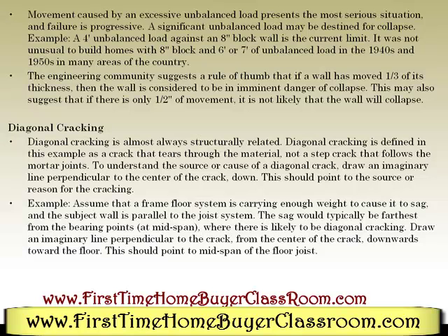The engineering community suggests a rule of thumb that if a wall has moved a third of its thickness, then the wall is considered to be in imminent danger of collapse. This may also suggest that if there is only a half-inch of movement, it is not likely that the wall will collapse. Diagonal cracking. Diagonal cracking is almost always structurally related.